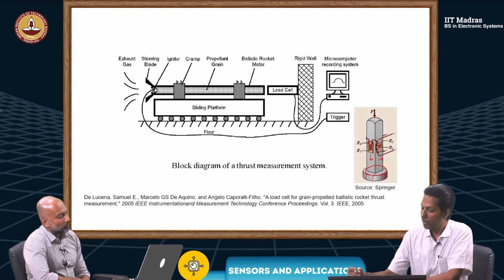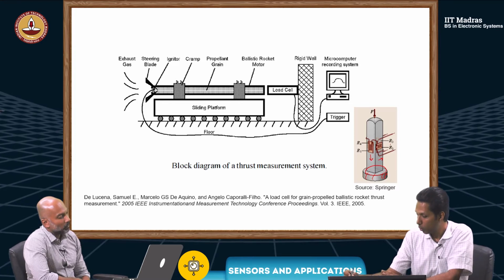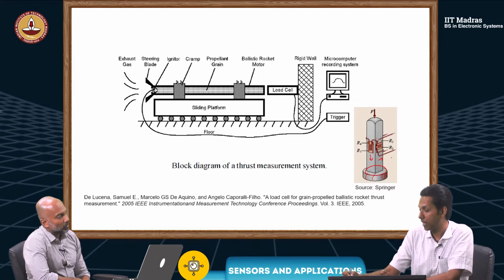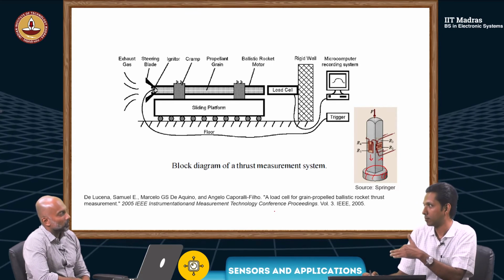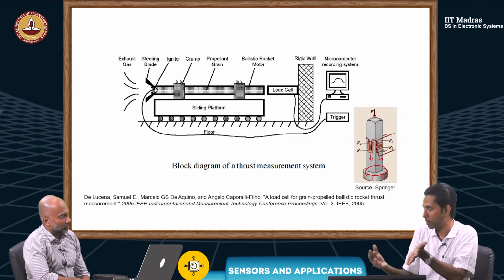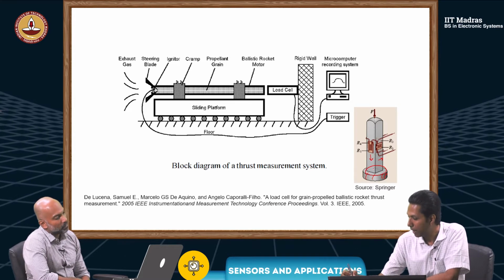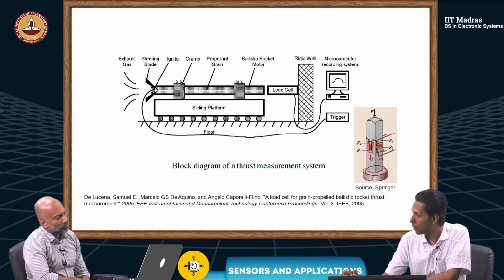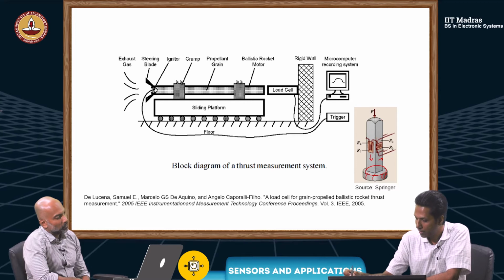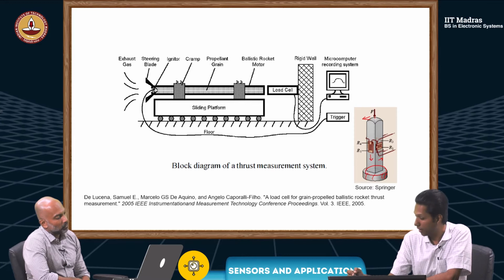The other two faces will be similar: there will be one more that is sensitive to compression and one more which is sensitive to the expansion. So you get four sensing elements in the push-pull fashion, so you can form the full bridge, right? Now, if this gets bent from here, let's say there is a force in this direction also.